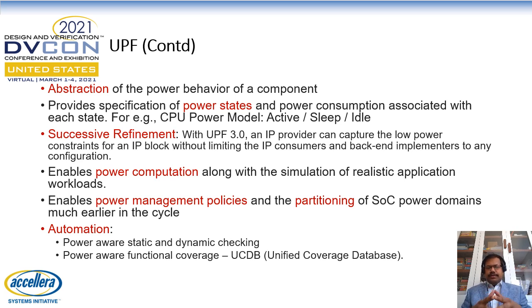When we look at UPF 3.0, one of the things that it also allows is the complete automation of power aware, static and dynamic checking entirely through tools. We don't have to eyeball complex logs or other things to figure out. It allows the complete automation of this entire step. Also, it allows automation of power aware functional coverage, which was not possible earlier, by capturing all the relevant details and logging it into the UCDB or the Unified Coverage Database.